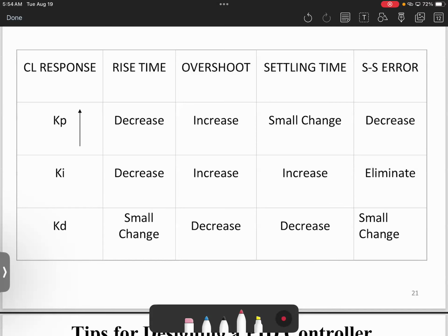Again, assume you have the design choice for an elevator. What's the best controller? P, PI, PD, PID? PID, of course. Why? With a PID we don't have steady state error and we don't have overshoots, so it will be smooth from floor 0 to 100 without a problem.